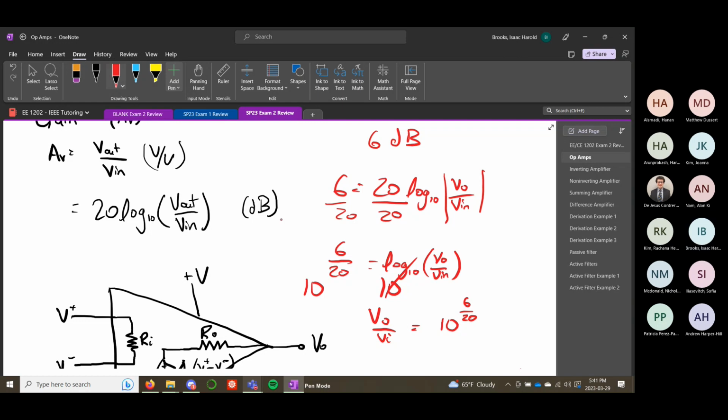But the gain in decibels can't really tell you if it's inverting. It can only tell you if it's bigger or smaller. So a negative gain in decibels, like -3 dB, doesn't mean that it's inverting the signal. It just means that it's attenuating it by 3 decibels, so the output is 3 decibels lower than the input. So don't worry too much about the sign of it. Of course, for this class, there may be questions like, does this circuit invert it? Is it going to be negative? But when you're worried about the decibels and the logs, just take the absolute value. Good question.